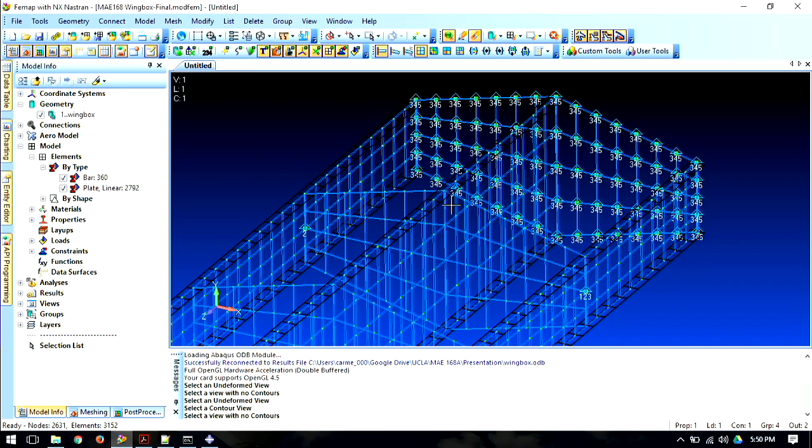Are any of these composites? No. But in your application, they're probably composite. Yeah, I deal with mainly all composite, but the loads portion doesn't change in terms of extracting the loads. The loads that you see in the composite, it's going to be the same procedure. It's just how you size it and what kind of theory you use. So there's laminate theory, and the buckling is pretty similar, because you can get your laminate isotropic properties for the composite from your ABD matrices. I won't go too much into that.